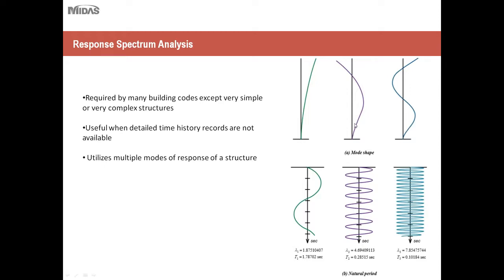Some of you are probably wondering what these pictures represent. When you're doing a response spectrum analysis, you'll have several modes that you'll be studying. Each of these pictures below represents a different period of the wave. For example, let's say the earthquake just starts, and this is what the vibration looks like, and this would be the mode associated with it. However, when the earthquake picks up, the frequency or the intensity and strength of it might increase, and then you would have a different modal shape.